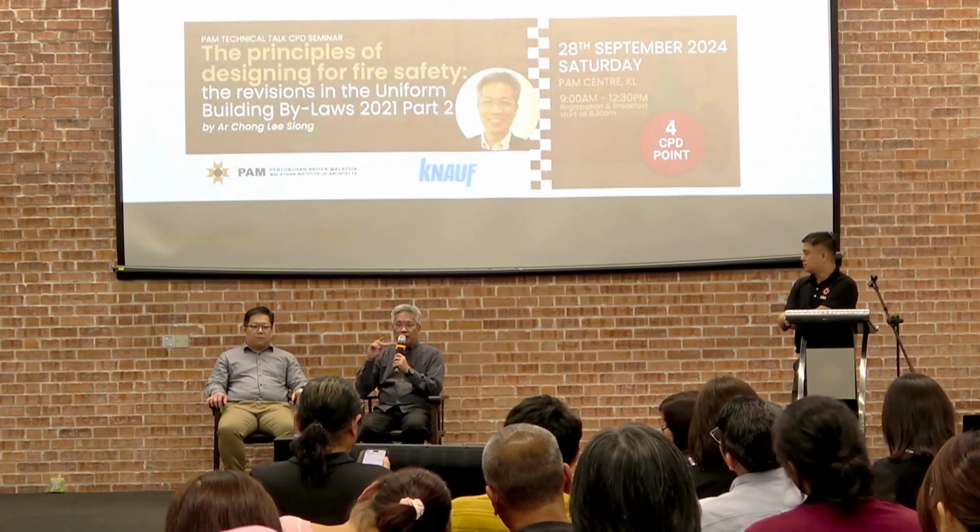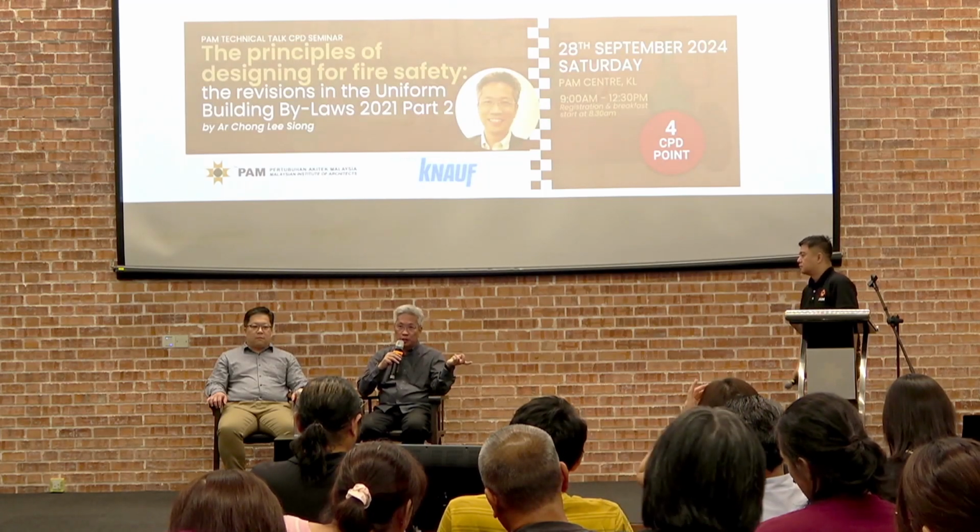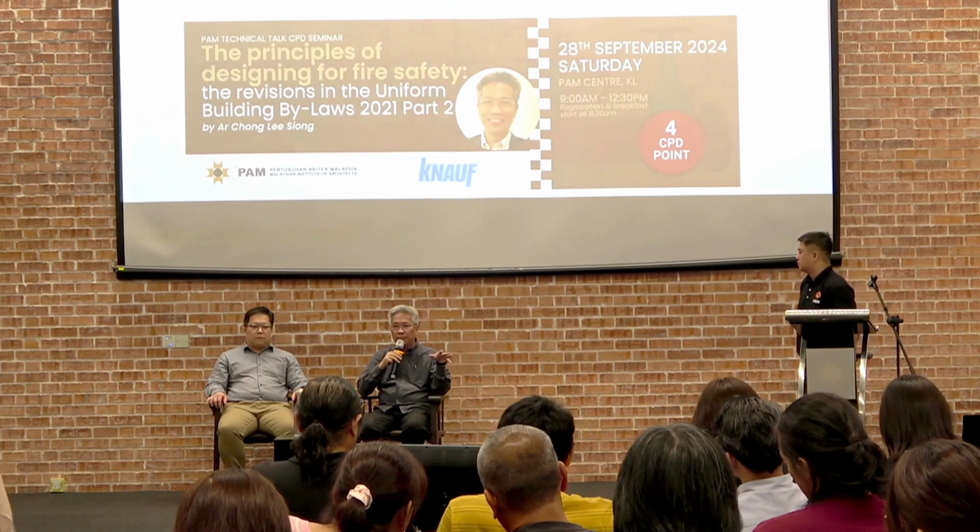The primary inference is actually from the very, very old British ordinance, where individual lots, landed properties may be built at different times. So the 100 millimeter minimum thickness is something that is meant for you. What they're saying is that if you're having a wall with your adjacent neighbor, you need minimum 100 millimeter of solidness between you and the neighbor.